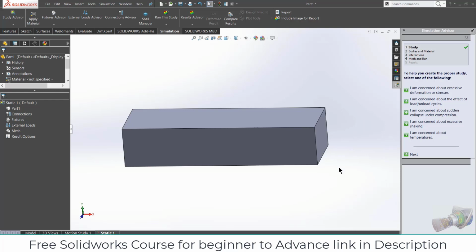For those who are wondering how a ductile material can convert into a brittle material, ever saw the movie Titanic? Have you ever wondered why the Titanic sank when it collided with the ice tip? Why didn't the ship just bend? Why did it break down there? The reason is that engineers learned that at very low temperature, a ductile material will act as a brittle material. That is the reason the Titanic sank. They discovered this from the Titanic case: your steel metal material will act as a brittle material at low temperature.